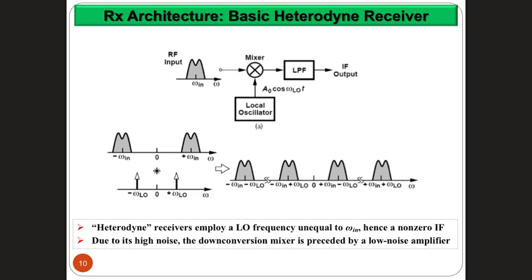Now the end result of doing this, as you might already know, is that I'm going to have the signal appearing at WN minus W local frequency, positive and negative side, and also at WN plus W local frequency, positive and negative side. Now, since I'm doing low pass filtering, I'm focusing only on this part, right? I'm only cutting this part and suppressing the other ones.